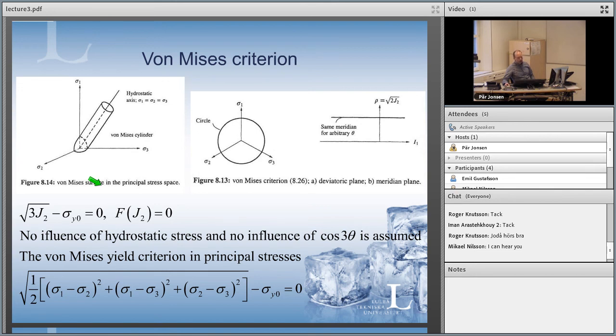This is what you do with this coordinate system, this simplification. So for one pressure point, you only work in this area here, and this is your deviatoric plane. It's also called the pi-plane sometimes in the book. It's only a circle on a plane. These are the projected axes, sigma 1, 2, and 3, and then you have your polar coordinate system with your theta.